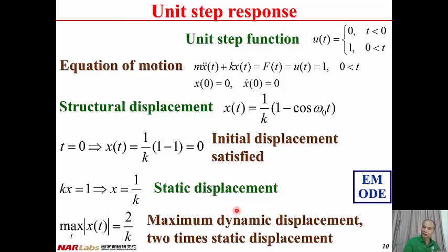Therefore, under static force, the displacement is less. Under dynamic force, the displacement is larger. It can be called the dynamic effect of the force. Therefore, the structural displacement vibrates at a frequency omega 0, but it does not vibrate about 0. It vibrates about 1 divided by k, that is the static displacement. Therefore, the structural displacement vibrates about the static displacement, between 0 and the maximum dynamic displacement, 2 divided by k.